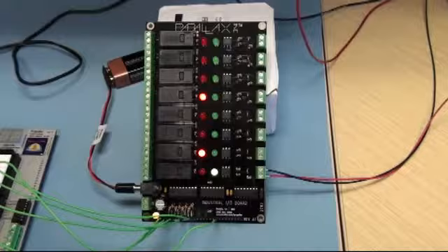So if you're kind of a novice at controlling this stuff and you just want to do high-low to control the relays, or kind of read the status of a bit to read the inputs, you can do that. Or if you want to conserve pins and you want to shift out your data and latch it to control the relays, or latch and shift in your data to read the inputs, you can do that as well.